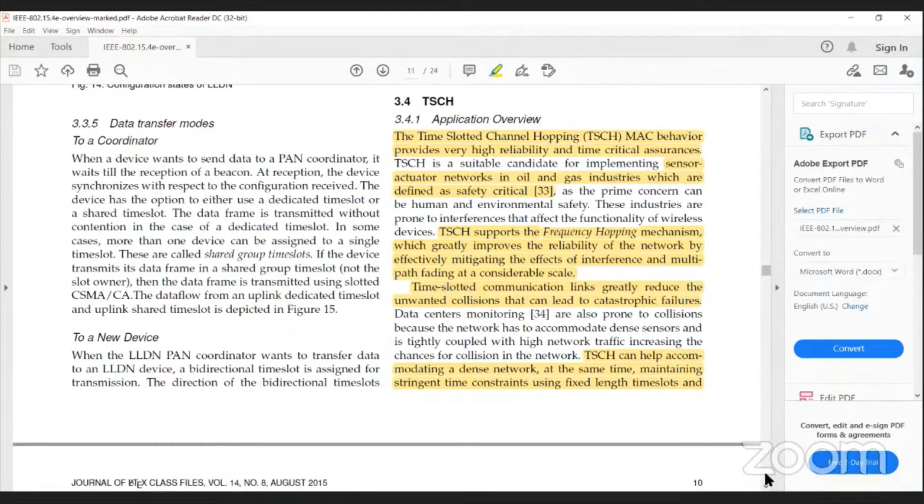Folks, if you come from an industry background, I can tell you that PLCs, the programmable logic controllers, are the ones vastly used in process control. In any process mechanism there is a schedule, and the PLC is programmed to follow a particular schedule. Every time it goes from one part to the other, it may do some sensing and then report back, say that the pressure here is so much, or the temperature there is so much.